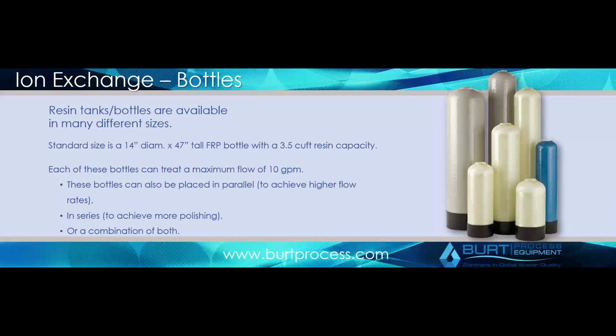The resin itself, while not hazardous, does have these ionic species in there, and then needs to be regenerated. That regeneration process involves the use of acids and bases, so it is a bit of a messy thing. It does require a fair amount of service, and depending upon how much pretreatment you've done upstream, your resin can exhaust very quickly. Traditionally an ion exchange bottle may last, with proper design up front, maybe a month. Without an RO, a resin bottle can be used up in a day, essentially.